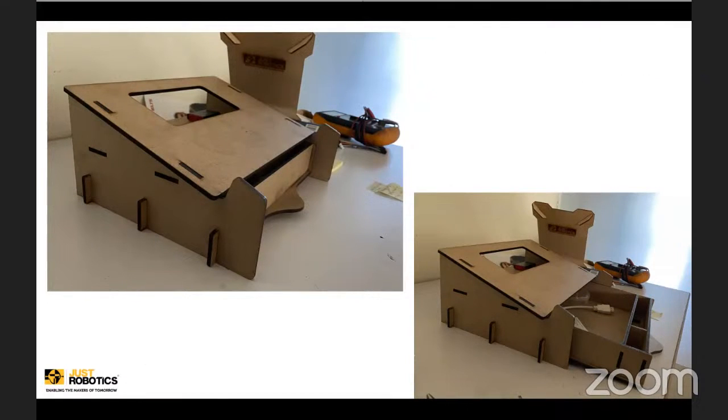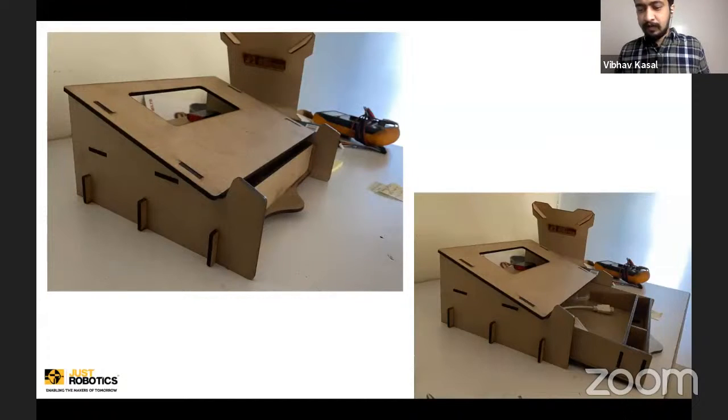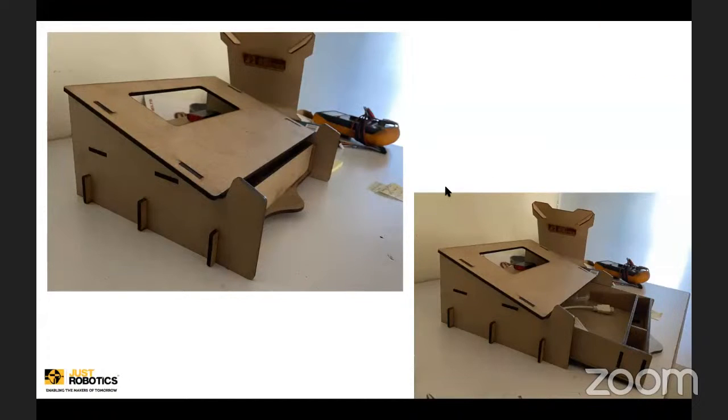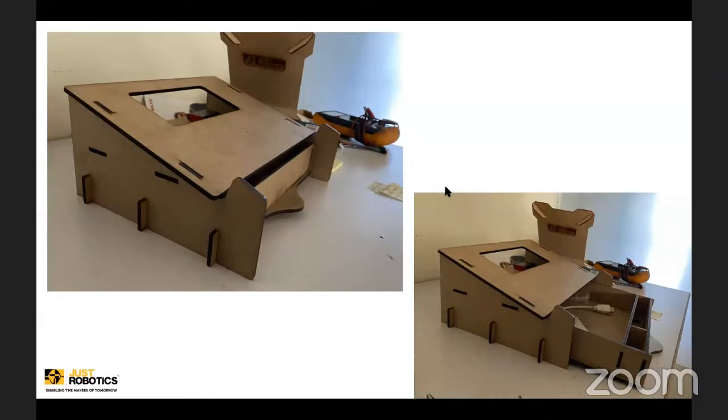Is the burn mark the only difference, sir, or do the finishing and smoothness also matter? If you cut it very fast, it won't reach that depth. Since the thickness is 3 mm, if it is going really fast, it will simply etch, because it is not getting enough depth. The laser has to penetrate the entire surface through and through to get a cut. If you go very fast, you will not get it. So this is something you should not worry about so much.